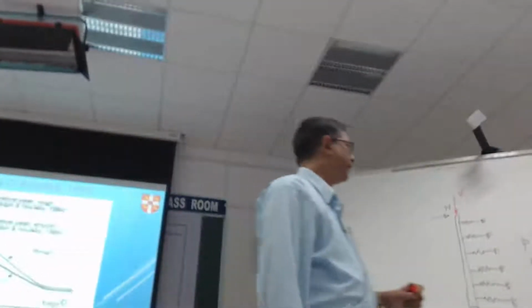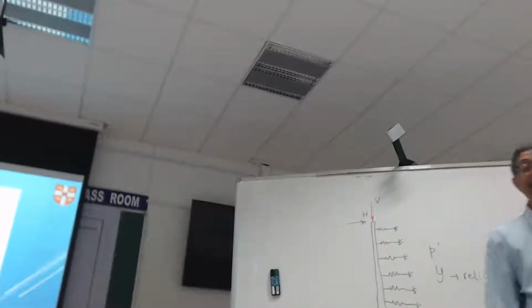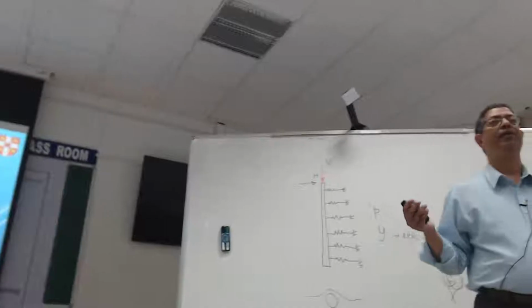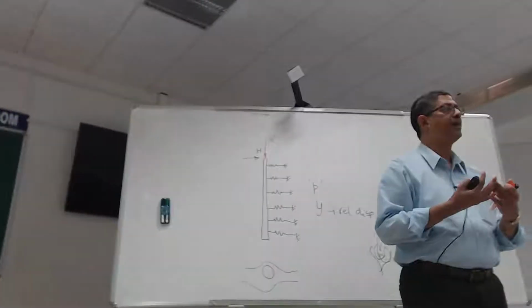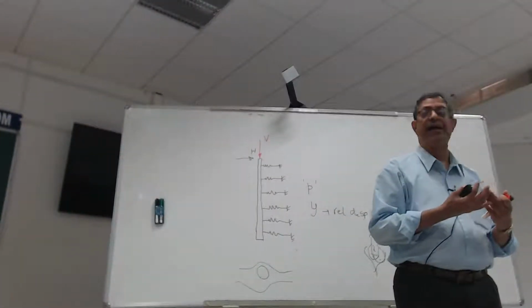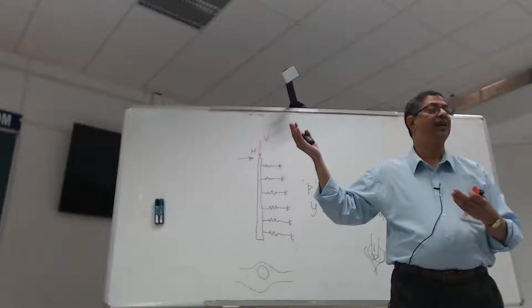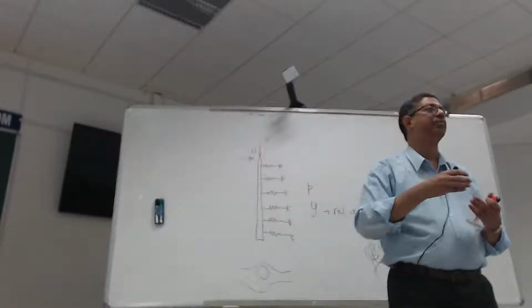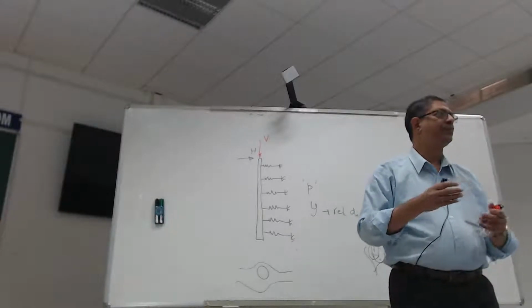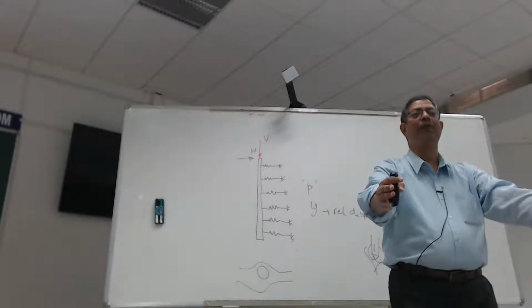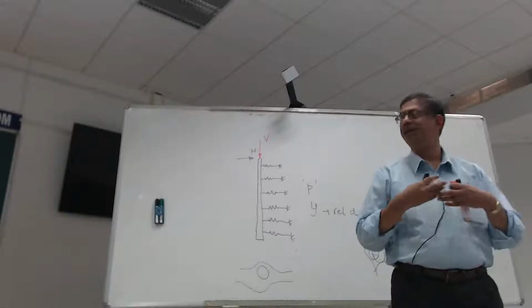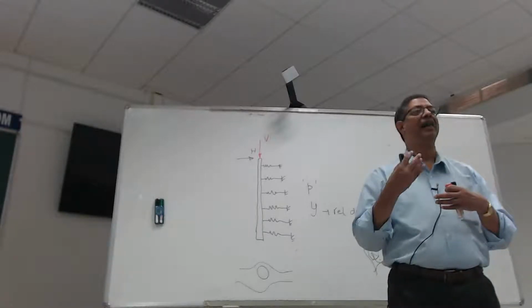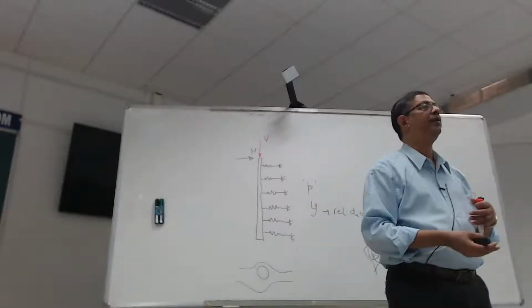The other nice thing about this particular piece of work is that they took the data from RPI centrifuge tests and they fitted this to that data. Okay, so they got a bunch of experimental data of piles in liquefiable soils and said this curve fits them nicely.